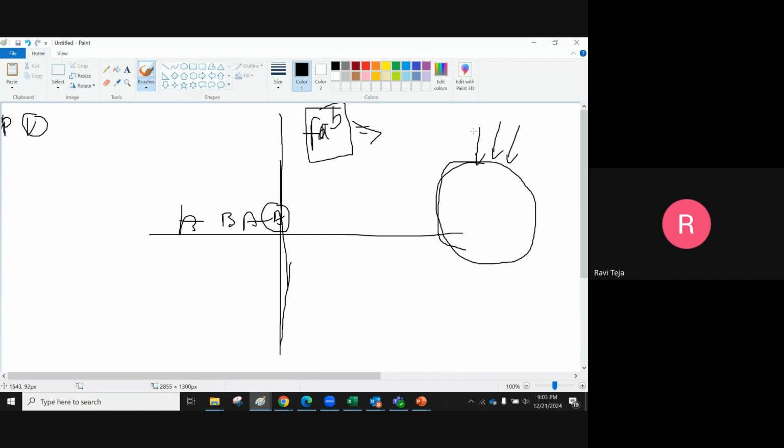imagine we are doing some ion implantation on this. Throughout the wafer, the ion implantation will not be the same. So here it will be different, here it will be different. It will change from the center to the edge; the implantation may vary. Here it might be more, like more ions, and here it will be less, so it is not uniform. As it is not uniform, you cannot simply place matched devices.